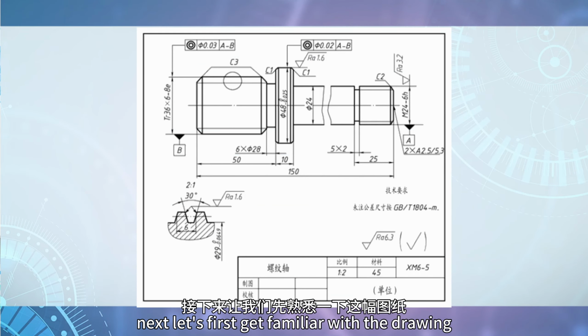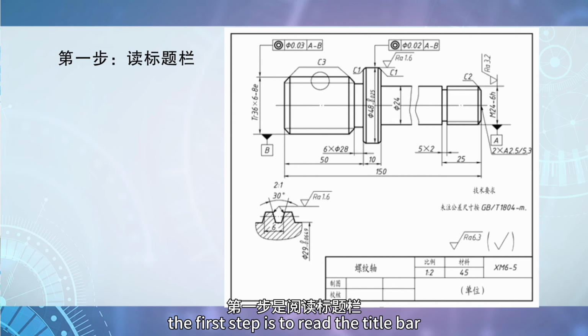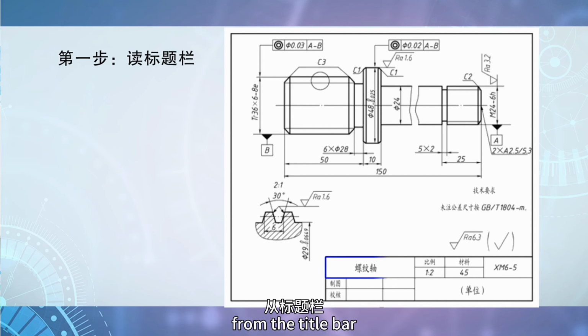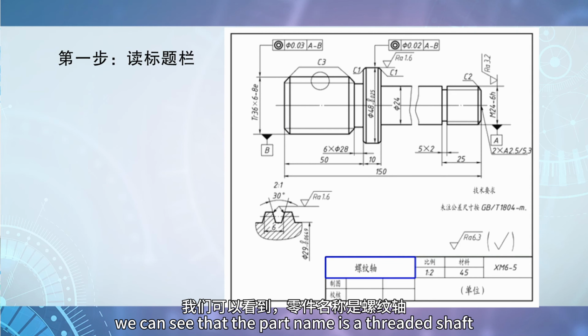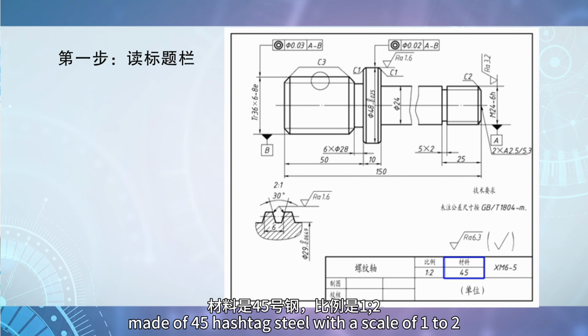Next, let's first get familiar with the drawing. The first step is to read the title bar. From the title bar, we can see that the part name is a threaded shaft, made of 45 steel with a scale of 1 to 2.